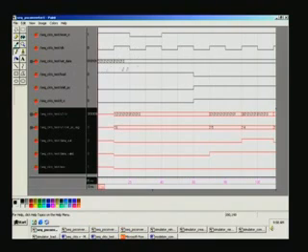You can see that load is high here, and so shifting starts right at this point once the load is complete, and simultaneously you also assert shift right here, and what happens after this is the 1010 pattern shift register will be shifted 1 bit per cycle at positive edge of the clock, that's here.